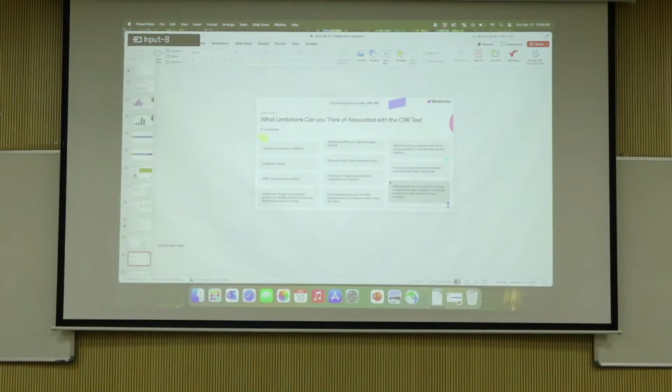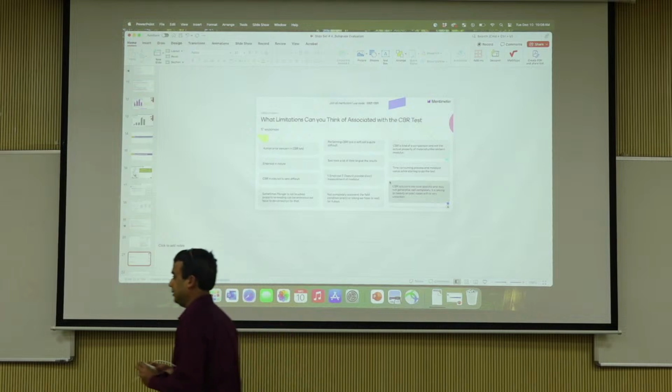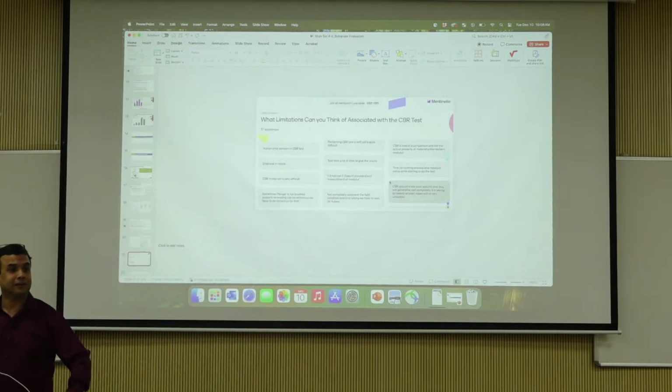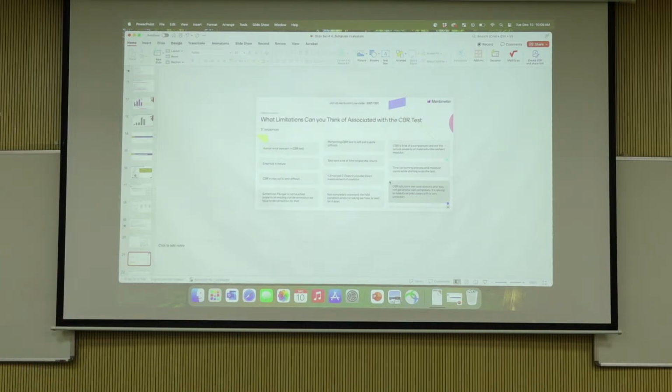What kind of loading do you experience in a pavement? Who said cyclic? You're going to buy me lunch today. No cyclic. What did we say yesterday? Repeated, not cyclic, right? We don't load pavements in cyclic.